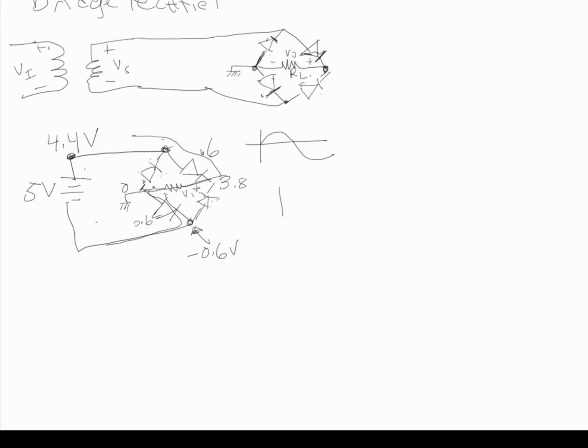So on each cycle, it's going to use an opposite pair of diodes. And so you can see that your V out is going to be your Vs minus 2 V gammas on this. Whatever Vs is, minus 2 V gammas.